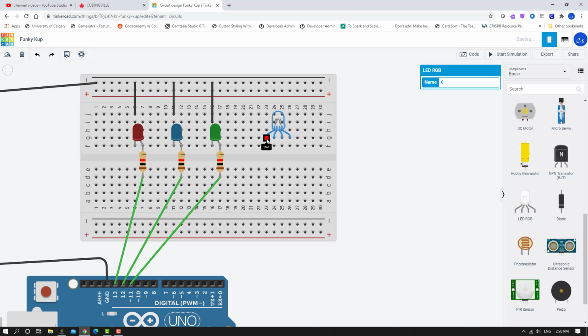What we can notice here is that we have a red column or a red pin. Okay, we have a blue pin and a green pin. These are called anodes. These are where we can have the electricity flow into the component. And then we have a cathode, which is called a common cathode. This cathode is shared by all three of these lights. So pretty much put simply, an RGB LED is just a single LED with three little small LEDs or diodes